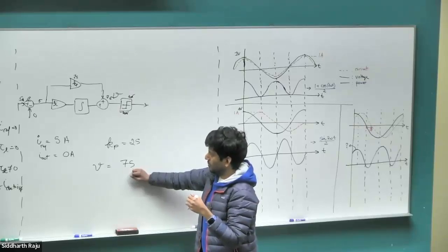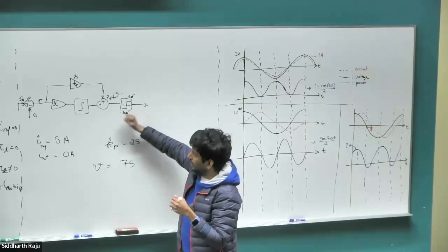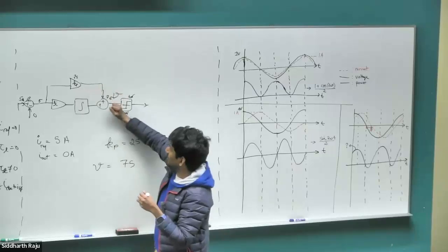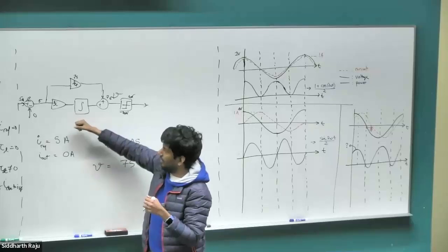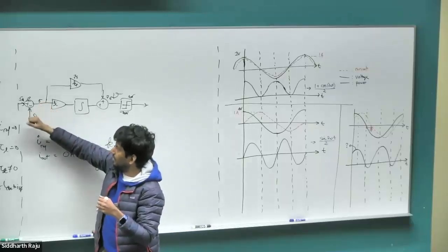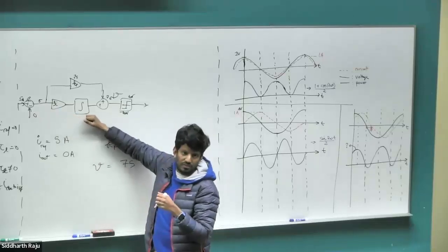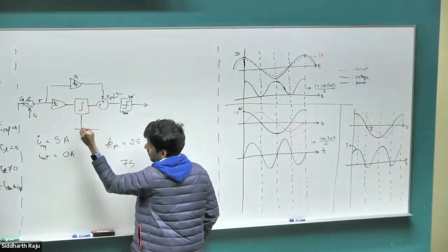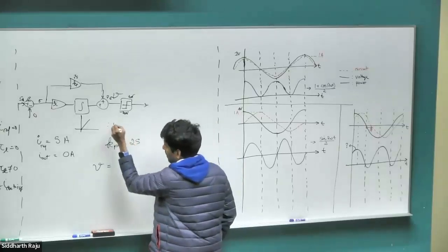There is still a little bit of a problem here because we have already reached the 40 volts that the power converter can generate, but the integrator does not realize that. So even though the Kp path has already tapped out its maximum, the integrator is still going to keep integrating the error because it's 5 amps required, 0 amp currently, so there is an error of 5, and with time it keeps integrating. So this value will start at 0, and it will keep going up and up and up. And this is called windup.